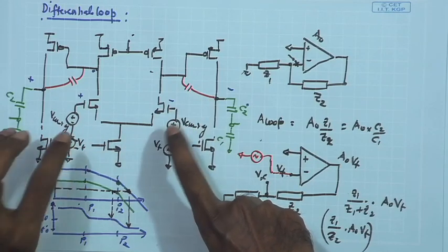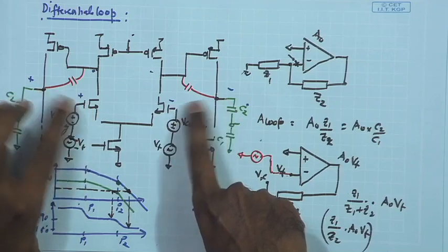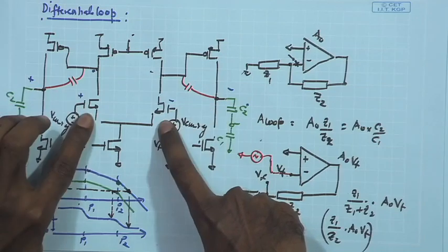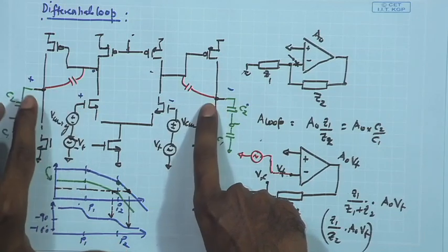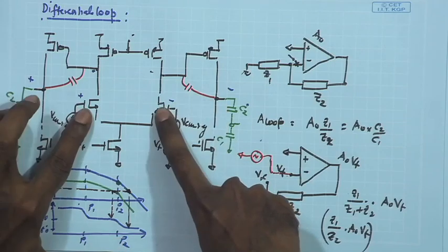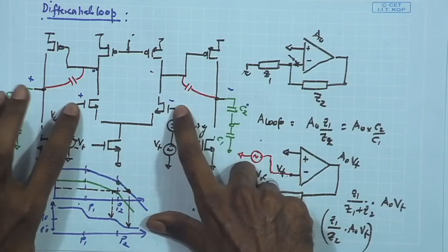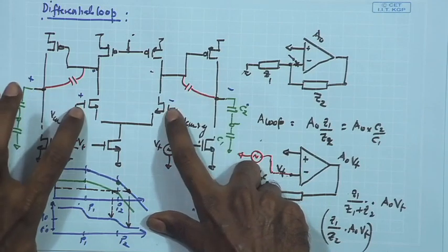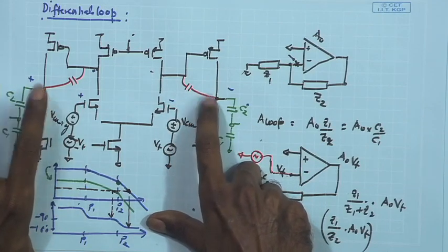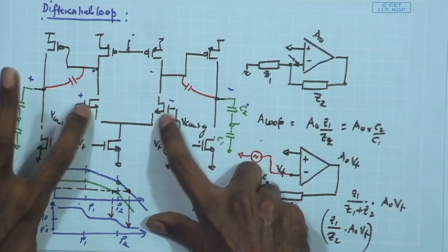In that case the RF is not playing any role anyway, so you can eliminate it altogether. Even its presence will not matter much. So, you can confirm that even if you have RF between these 2 points, that high impedance resistor that you implemented using transistors, it is not going to hurt much in the overall simulation, because there is very high impedance.